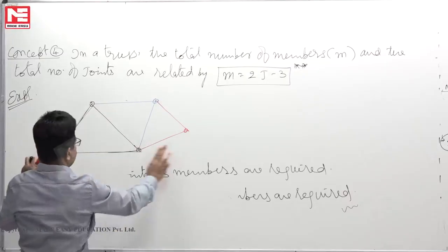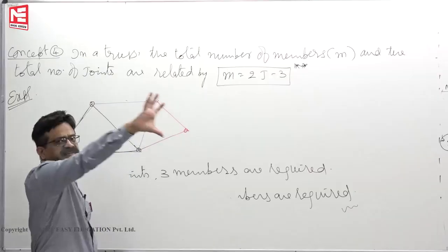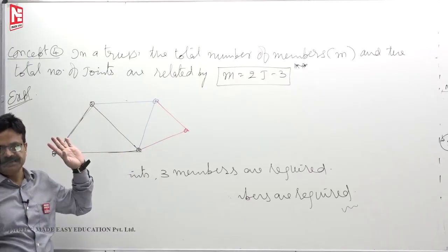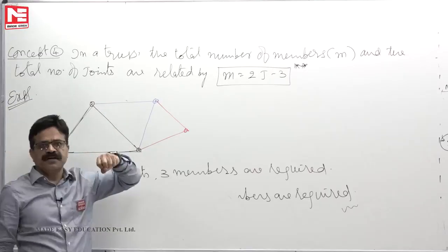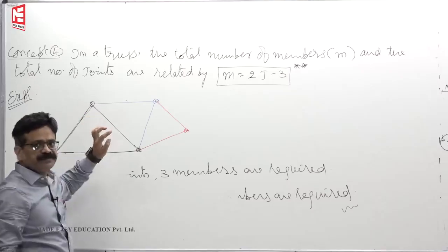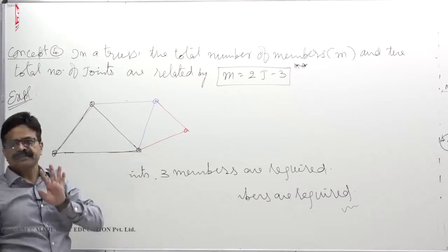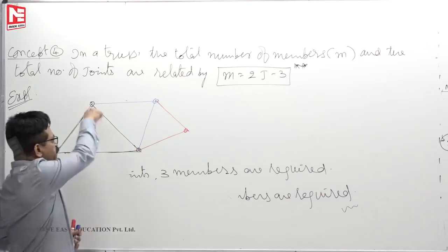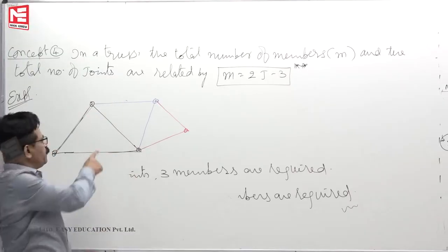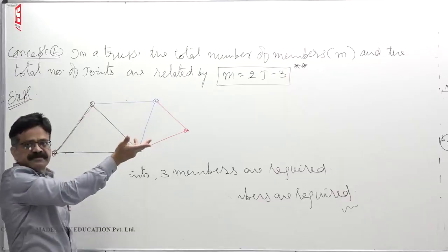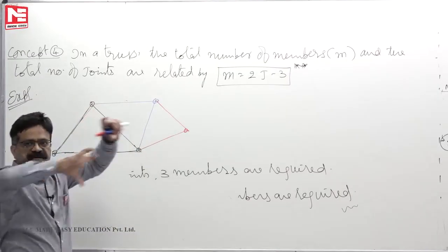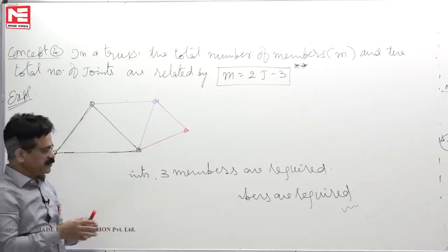You have built one structure, simply supported, a big structure. Assume that this member was under compression, and due to some unforeseen reasons, extra force came than what you expected. Because of that additional force, that member buckles, let us say. If one member fails, the mechanism, that means the triangulation, is gone. So this will collapse. The entire structure will fail because of one member.